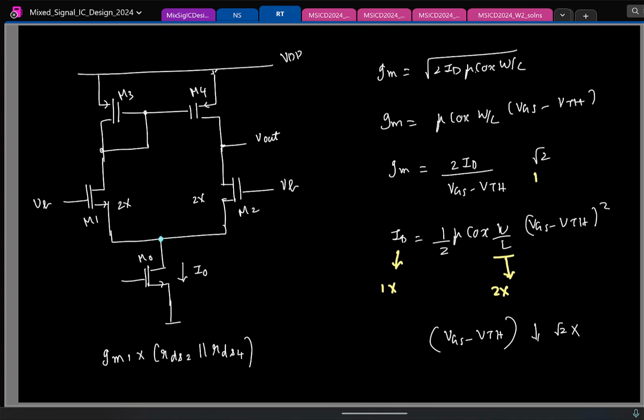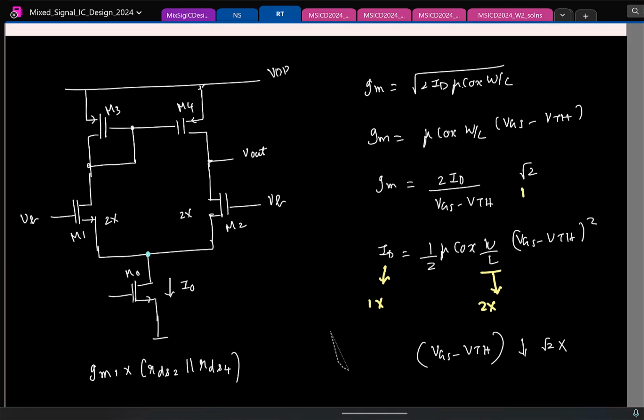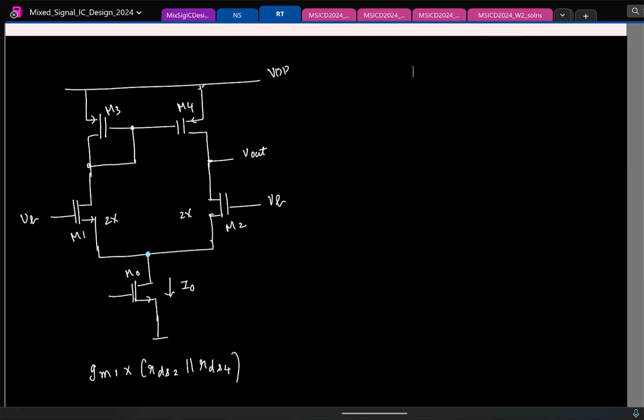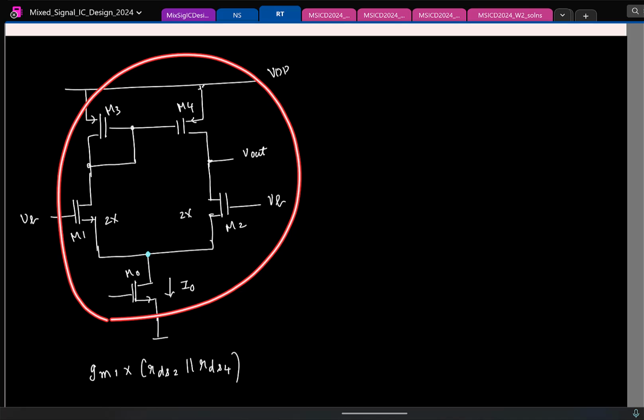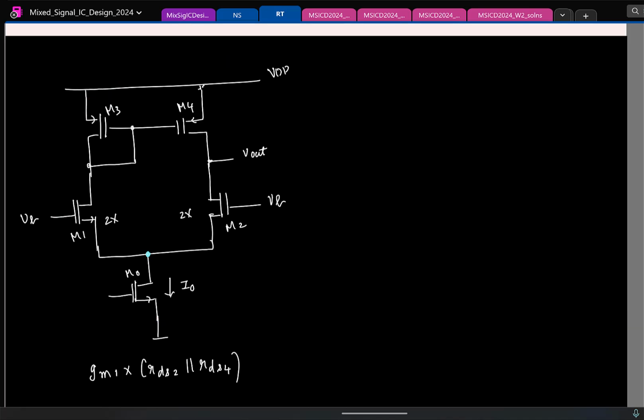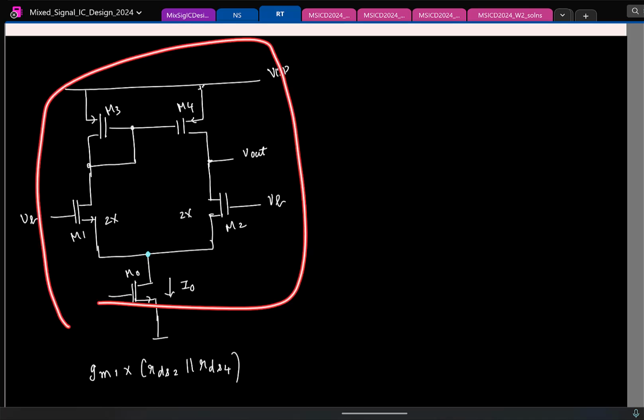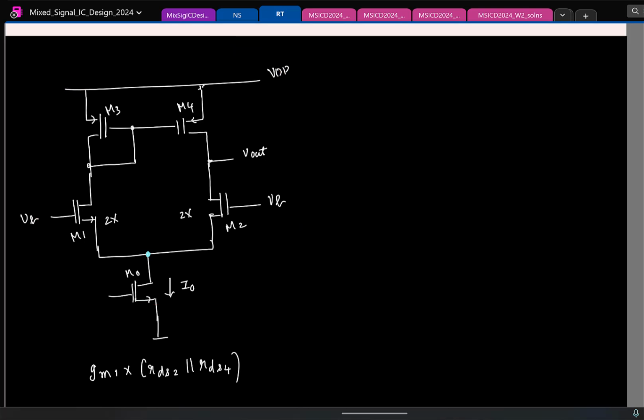And here, adding gain is easy or multiplying gain is easy? Multiplying gain is easy, but why is that so? See, I have some gain from this stage, right? I am saying this is not enough. I want to increase the gain. So what is one suggestion? Whatever you do, it's not going to go so much, so I cannot simply use this. So what can you do? Okay, I can basically put one more stage and cascade. Fine. So what kind of stage do you think I can put here?